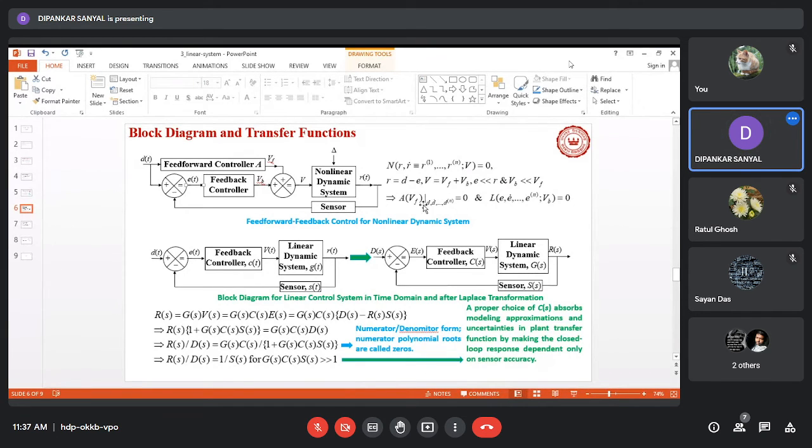Along with that voltage equation, we also obtain one equation for the error dynamics, where we have the feedback voltage that we manipulate so as to ensure that error proceeds to zero either asymptotically or over some finite time.